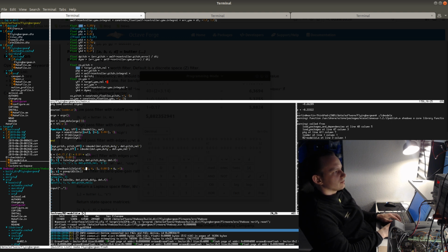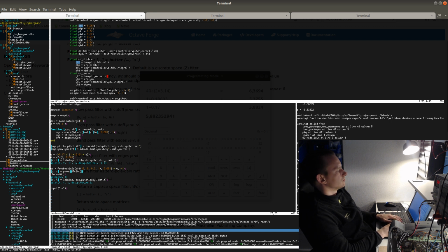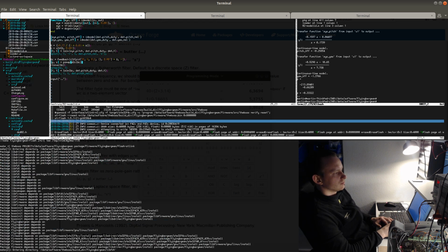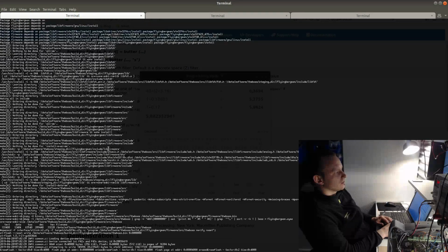Anyway, the values that I've arrived at using the simulation here are 18, 0, and 0.2, and putting them here also produces pretty good results. It gets rid of all of the clicking and jittering on the actuator.